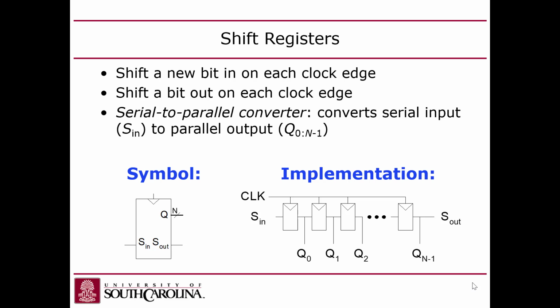But in practice, for these D flip-flops, the propagation delay is usually very safely outside the bounds of the aperture time, which, remember, is the time around the clock edge when you're actually sampling the data.